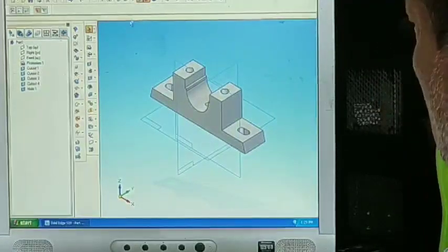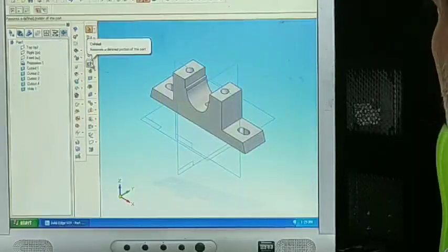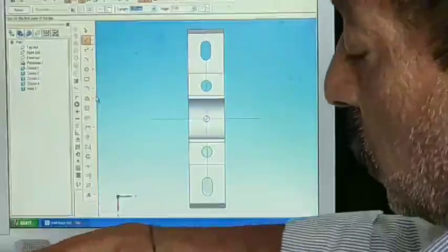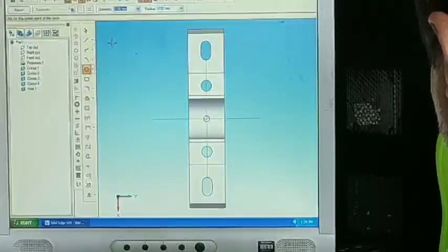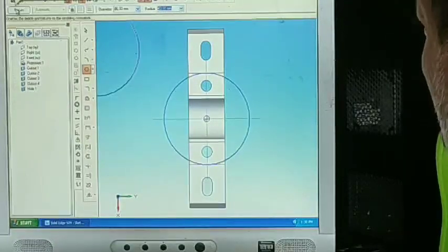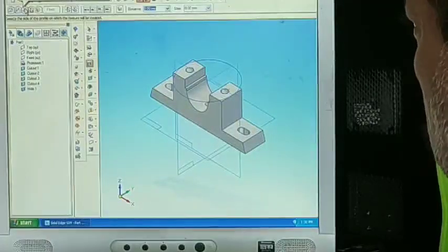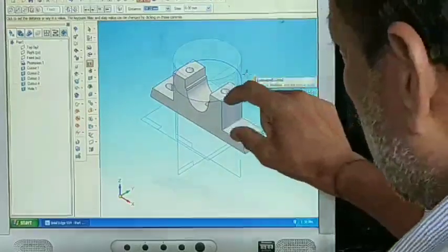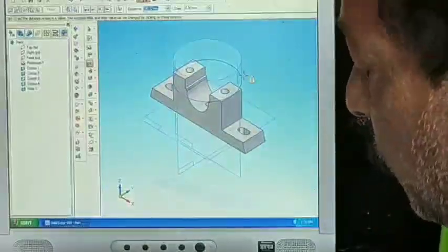So one more cutout is there. Around cutout. Select this face. Fit. So this distance is 86. So for that one, diameter 86. Fix it in the middle of block. Return. So here you go for cutout side step. Outside. So depth is for this much. Total height is 55. This height is 14. So total depth to be cut out is 44 mm.